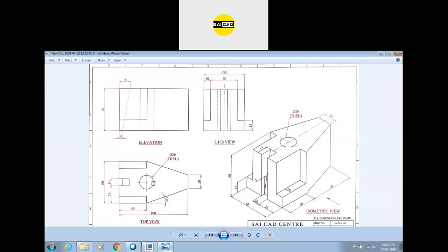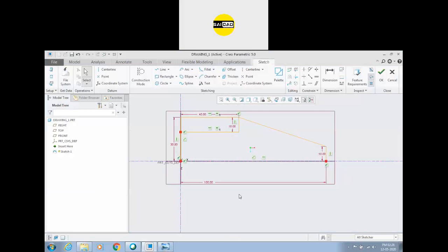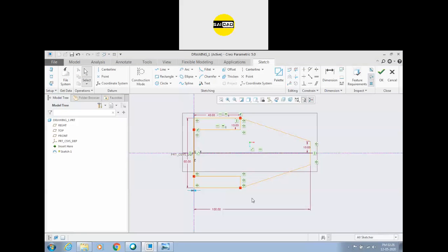So we have created half of the sketch. We can always use a command called mirror, but the mirror command is not available right now because we have to select an object first to enable it. So we can select all the objects, select the mirror command and select the axis. Now we can see the object is created.